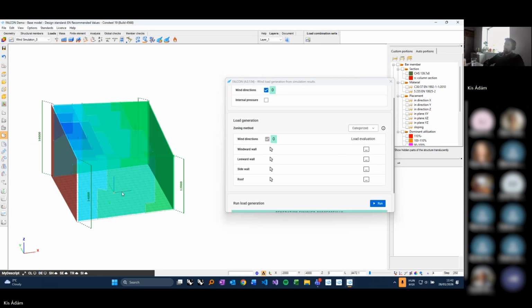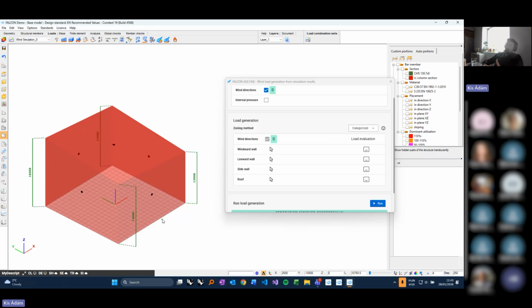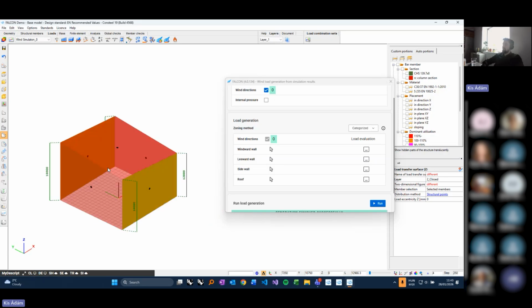is that we try to implement a solution which really tries to follow the procedure or the general approach of the Eurocode, where everything starts with defining certain surface types. Because in the Eurocode, you know that we first have to define the windward wall and the leeward wall, and similarly sidewalls, roof, and then we have separate values and other zones, A, B, C zones for the sidewalls.